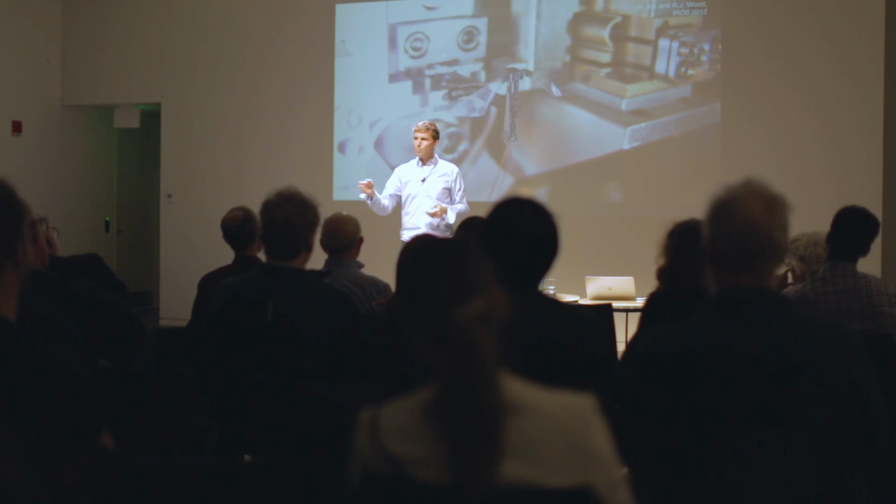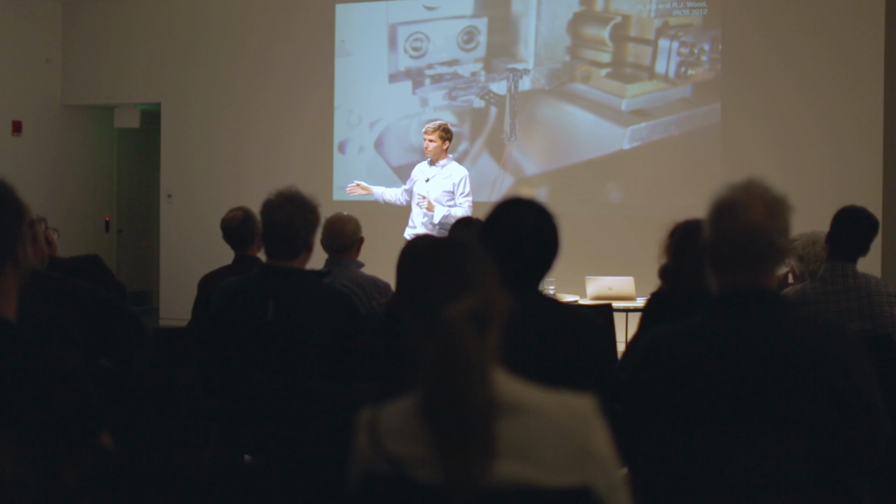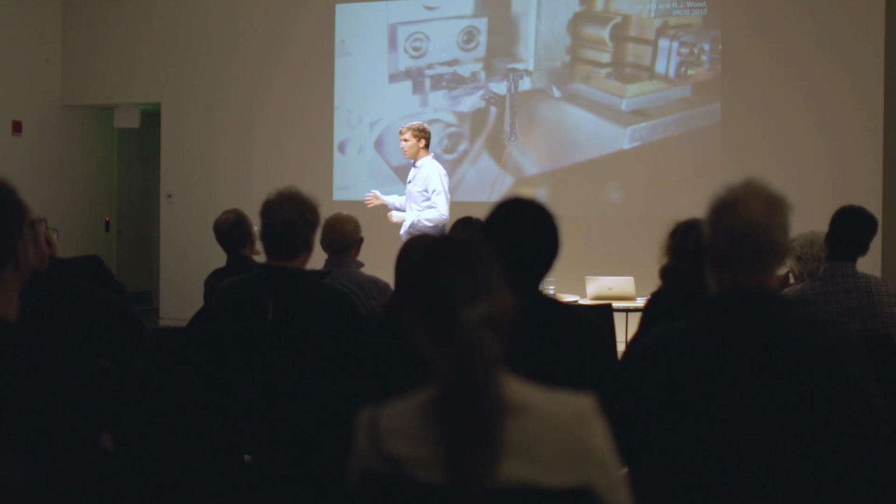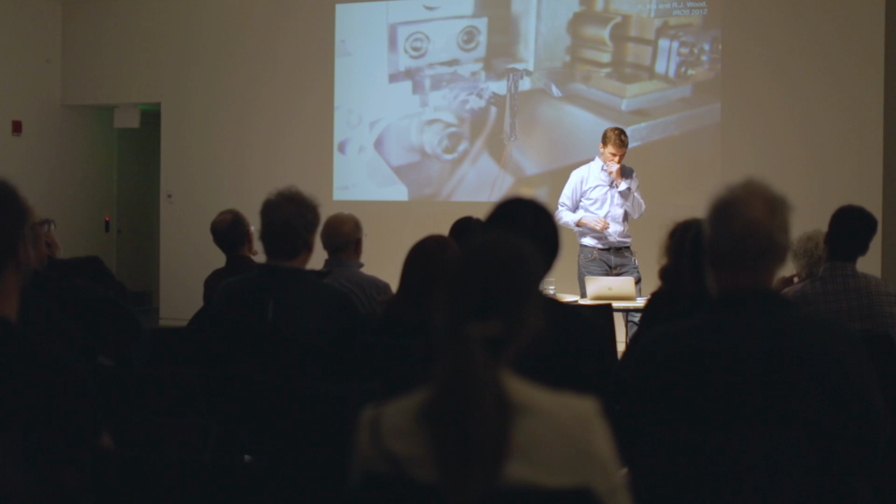And then yaw is a little bit more tricky. I basically have to keep the frequency fixed and have a faster downstroke than an upstroke. So I get this sort of paddling, I'm not doing this right, like that. I get this paddling motion with asymmetric drag. All right, so I can build these devices.